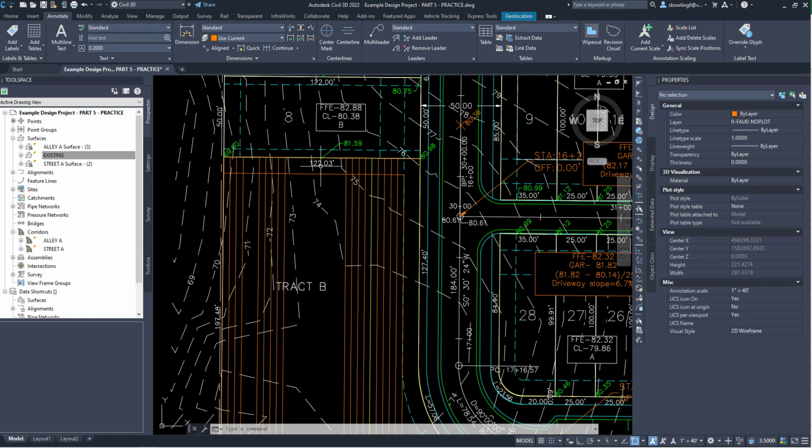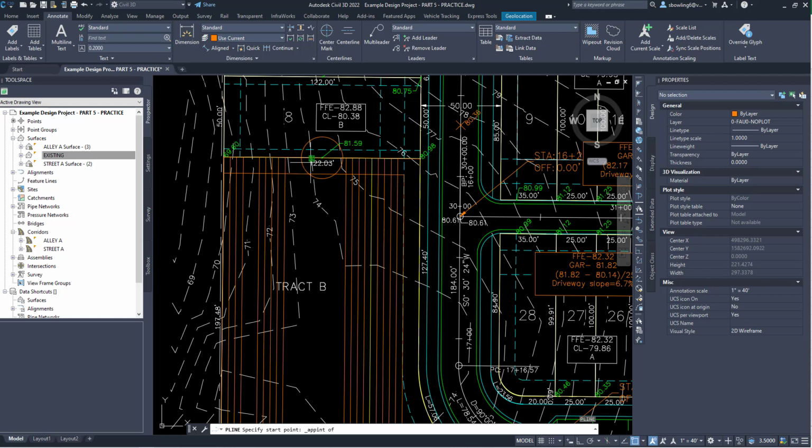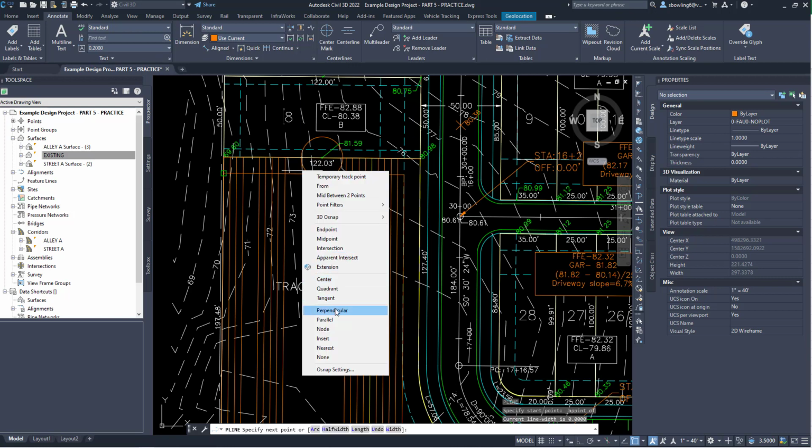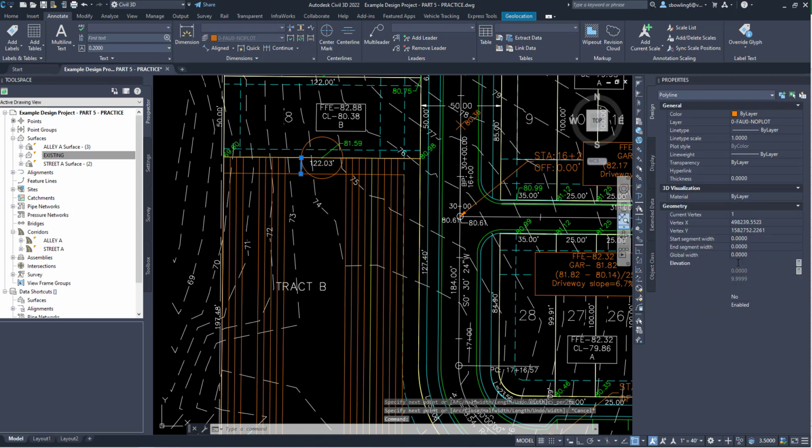That's basically 12.95 feet. So I'm going to draw a circle at 12.95 feet. So right here, and all I did was look at the slope and then figure out where the 79 contour would intersect. And I'm going to hit perpendicular to here. So that's going to be a 79 also.